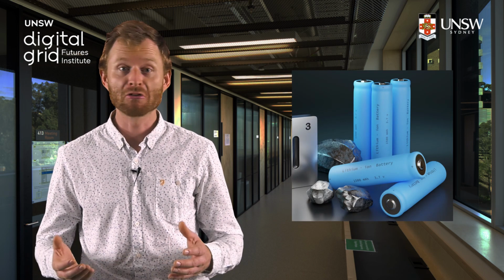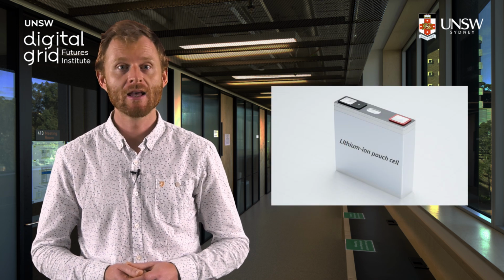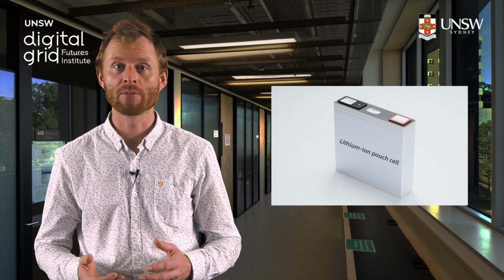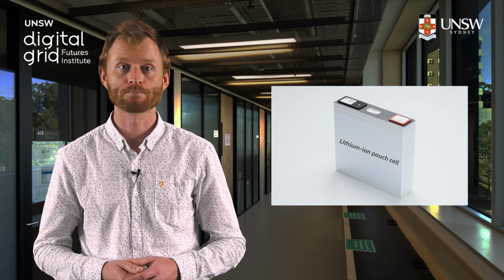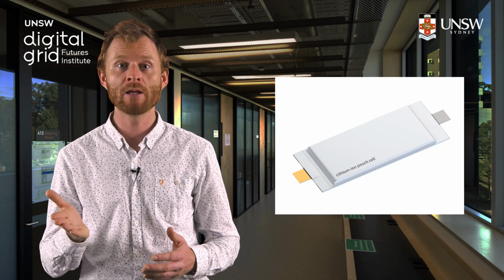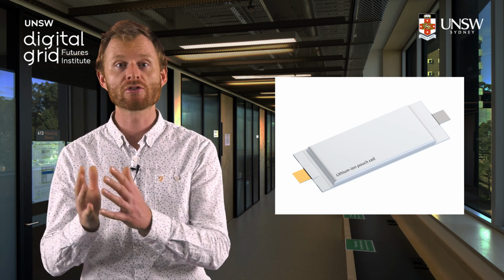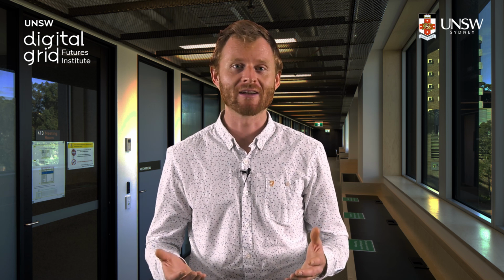Cylindrical cells have a cylindrical shape, like a AA or AAA battery. Prismatic cells have a rectangular or square shape, making them more space efficient and customizable than cylindrical cells. Pouch cells are thin and flexible, like an A4 sheet of paper. They are typically enclosed in a soft, flat pouch made from aluminium laminated film. Each form factor offers slightly different advantages and disadvantages, which we won't cover in this course. Just be aware that these different form factors exist.